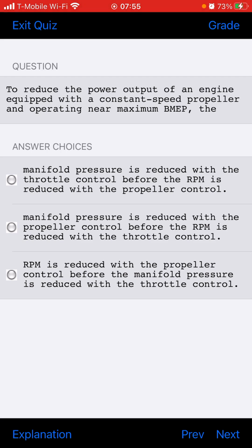So when I'm troubleshooting an engine and it has a malfunction, and I feel a cold cylinder, the others are hot, but this one is cold for some reason. You're telling me that there's lack of combustion in that cylinder? Yeah, that means there's lack of combustion in that particular cylinder.